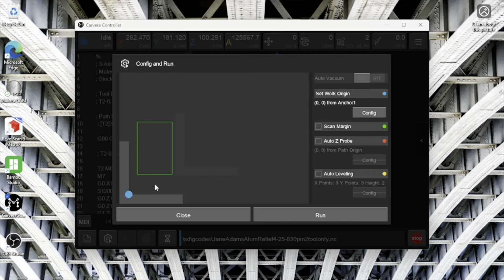Alright, so I had to run that toolpath again. So if you look, you can see a slight line. I'll try to zoom in here. And what happened was the collar was moved too far forward, and I never noticed that. So that's what was throwing the tool bit off. The reason it was just hovering just above is because that collar was too far forward. So I use this tool here to push the collar back up to its position because it'll only go to where that collar needs to be. So that's what you would use.